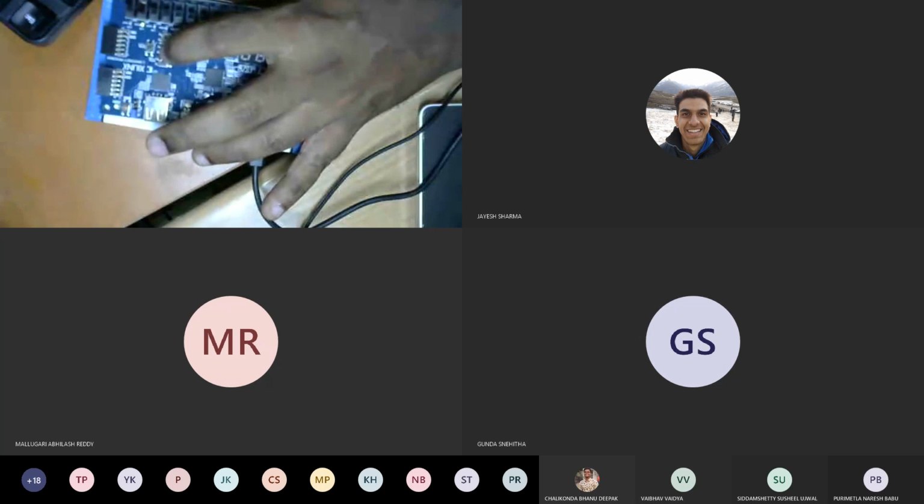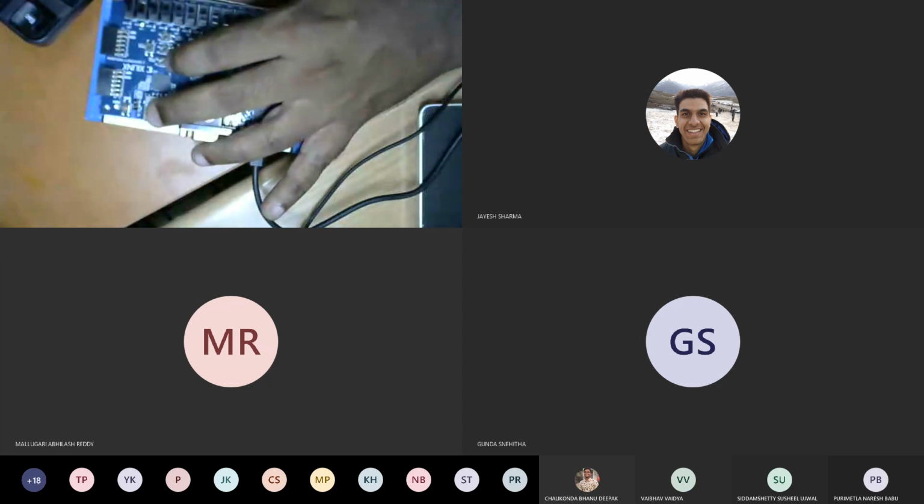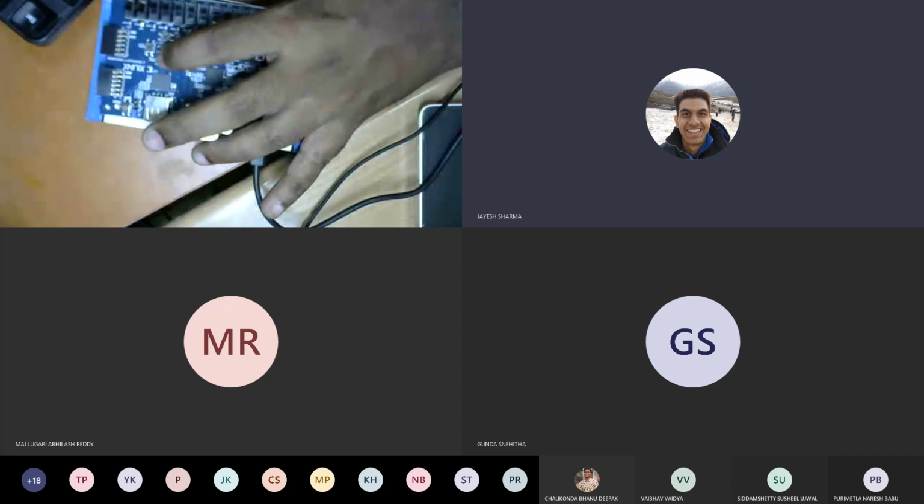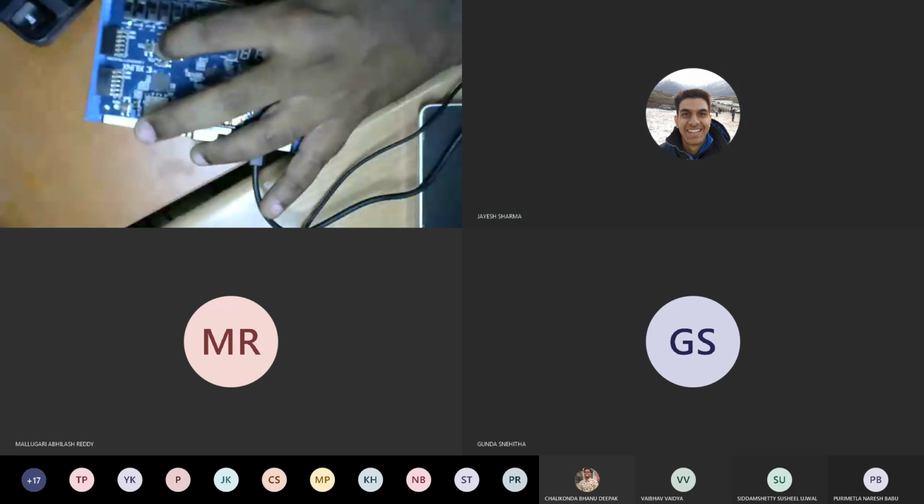But this time, now D equal to 0, I'll make sure that D equal to 1. Now D is in position 1, but of course it's not getting affected because we need an active clock edge. Now if I press this button, you're still seeing my screen, right? Yes, sir. The LED should flip. Yeah, now it's nice. Now if I press, Q should be 1 and Q bar should be 0, right?